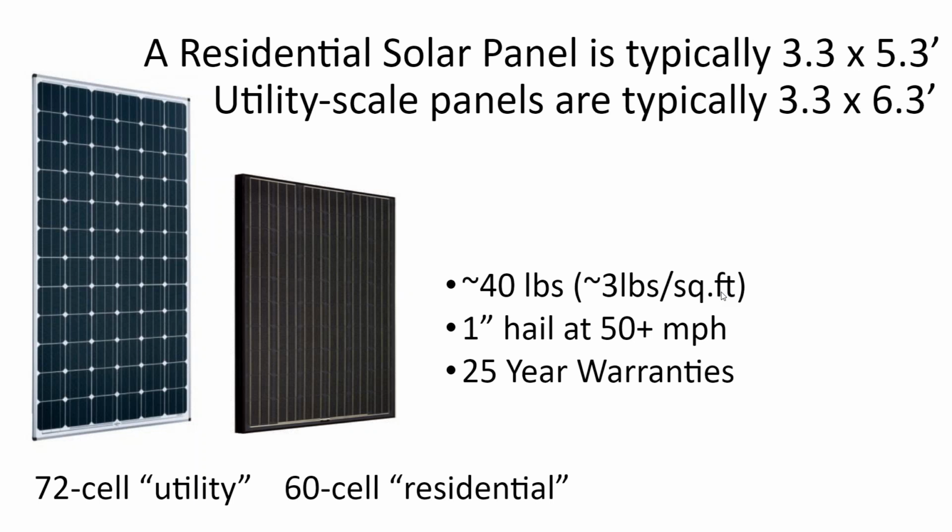So if you lean into a panel, if you walk on a panel, if you're shipping a crate of panels and you put stuff on top of it, those little impacts can shatter the glass. Or if they don't shatter the glass, they can form little micro stresses in that silicon that could, not always, but could cause the array to fail a little bit earlier in its life. Which kind of brings us to our warranty discussion. So before we get into that, just one little technical thing.